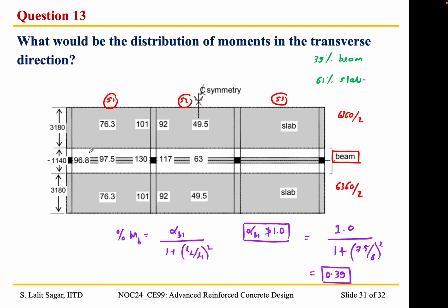So the thing is, when we are considering the exterior slab, we are not allowing the slab to take the exterior moment, so it is entirely resisted by the beam only. So if you consider the exterior slab S1, then the entire moment is resisted by the beam. On the other hand, for the span moment, it follows this distribution rule. Okay,